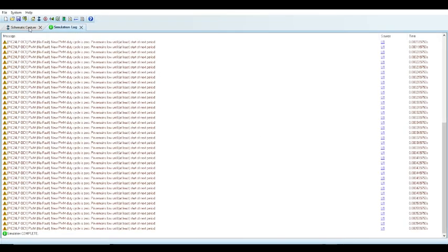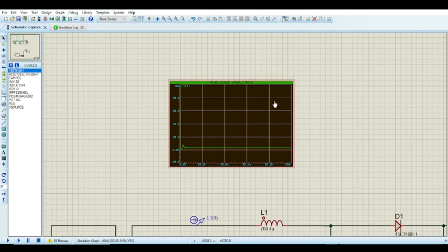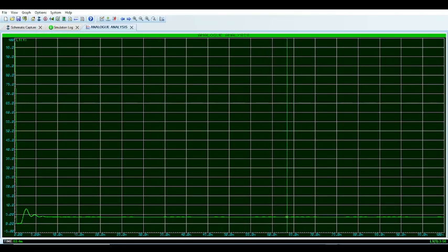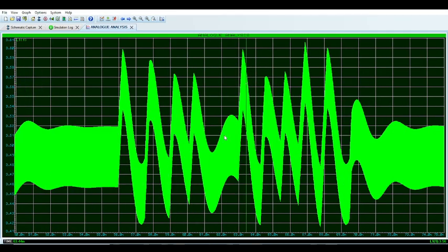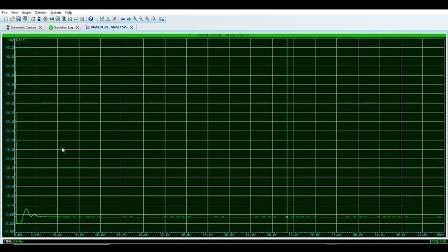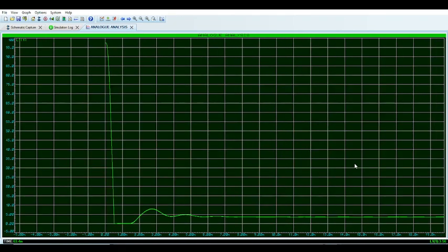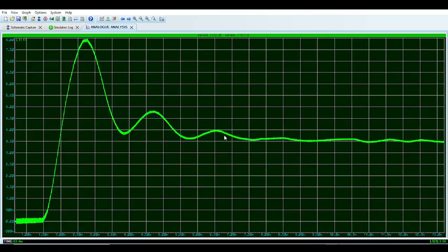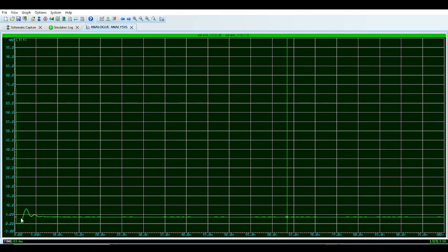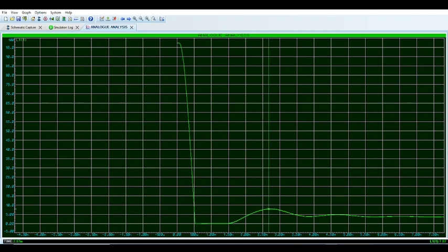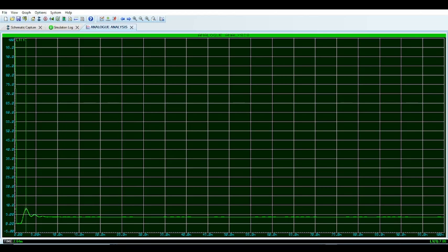And in a boost converter, that's easy to actually see. So I'm just going to do this. All right, so that's approximately 3.5. So that's a good thing, and it does it relatively quickly. That's about 7 milliseconds. All right, so that's good, I guess. Just see that it's 7.9. There's a bit of an overshoot, but that's fine. I think your inductor can take that. And it's a fast loop, so you expect that anyway.